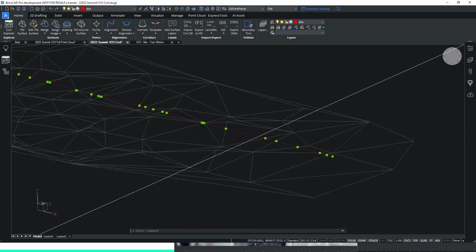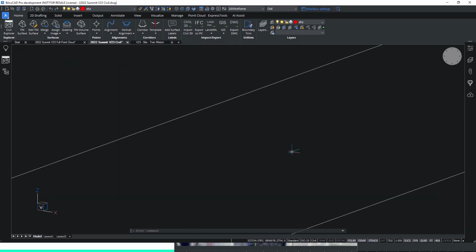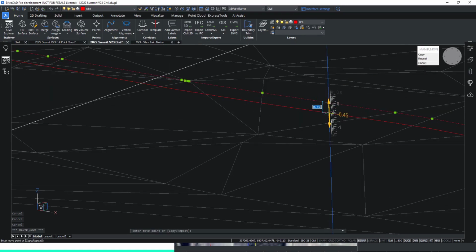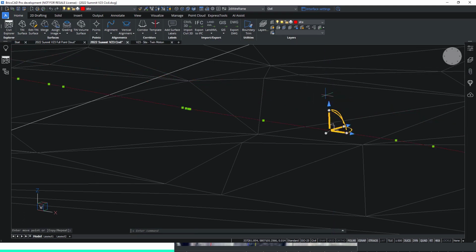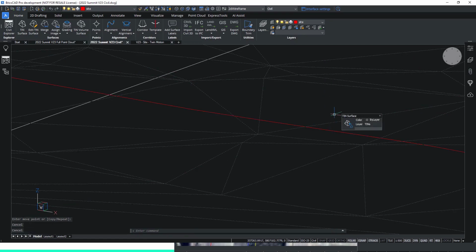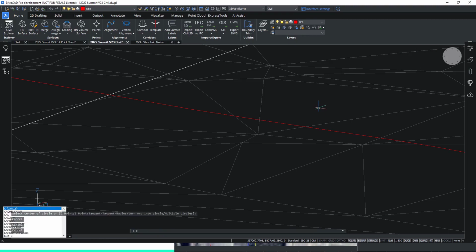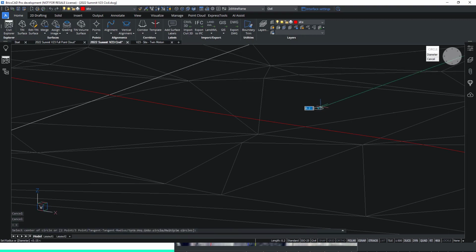What I'll now do is use the manipulator. Let's hold over this and lower this by the depth that we read from our attributes, which is 1.2. Let's type in 1.2 here. So to generate the 3D object, I'm going to do a circle and give it a radius of 0.15.